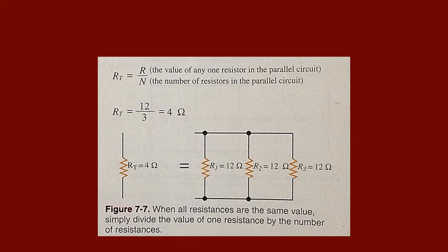Rather than having to use the total resistance equation for 10 reciprocals, the 8 like valued resistors can be turned into one equivalent resistance. 80 ohms divided by 8 produces an equivalent resistance of 10 ohms. Now add the two other resistors to your equivalent resistance using the reciprocal formula.